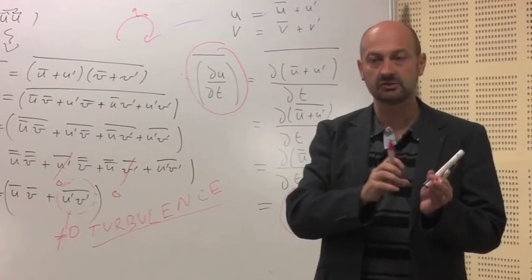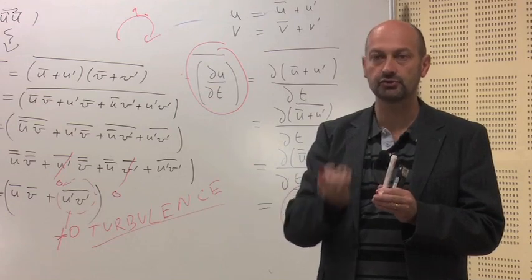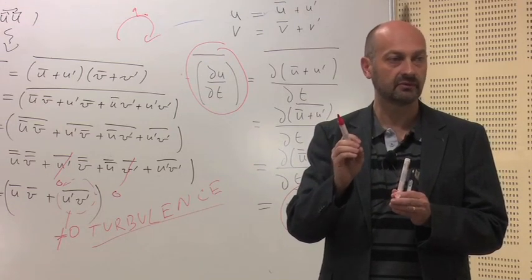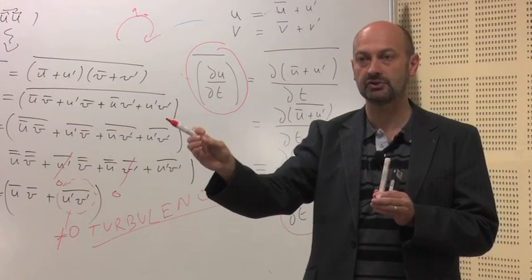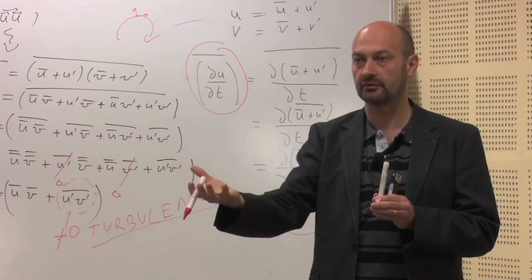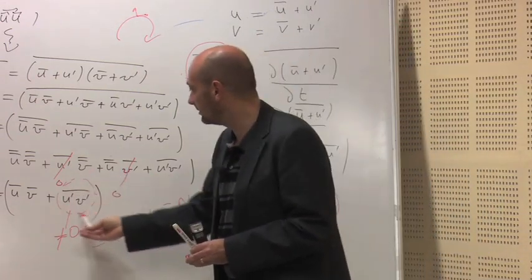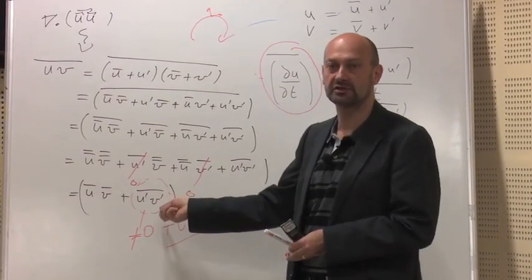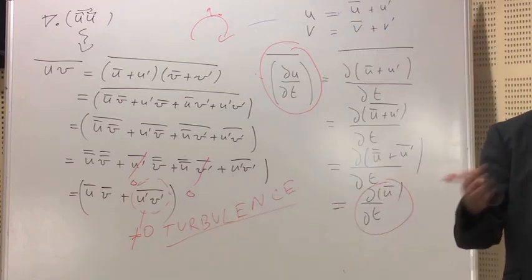The physics is connecting with the mathematical properties of the Navier-Stokes equation. The source of the turbulence is inertia. Inertia is nonlinear terms. When you increase the Reynolds number, you increase the weight of the inertia terms, and then you generate fluctuations, which is going to contain the effect of turbulence because it is non-zero. So this is the beauty of mathematics and physics and all these things.